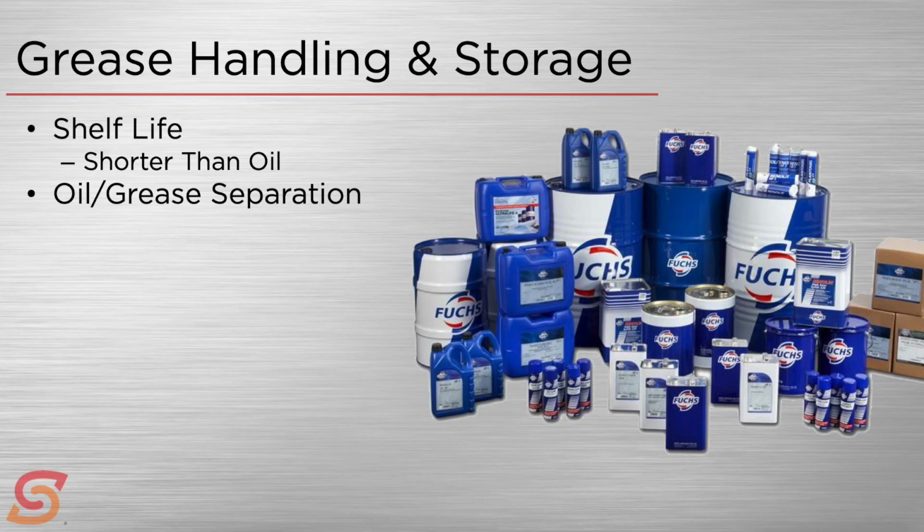Another handling thing about grease has to do with the oil separation. If 6 months ago you got a drum in, you take the lid off, and you're looking in there, and you've got a 1/2 inch of oil sitting around. Or maybe the surface is cracked. It looked like they had an earthquake or something like that. Geez, is the grease gone bad? Not really. That's a pretty common aging thing.